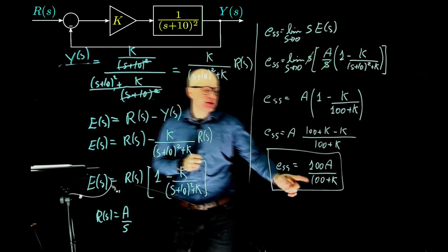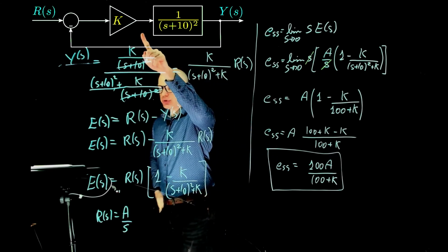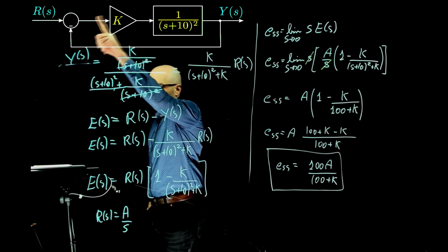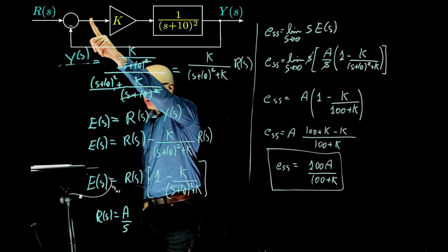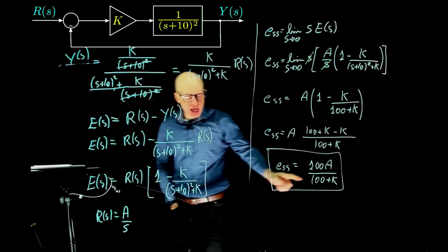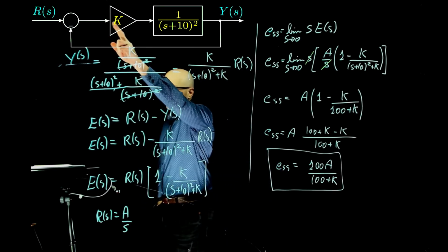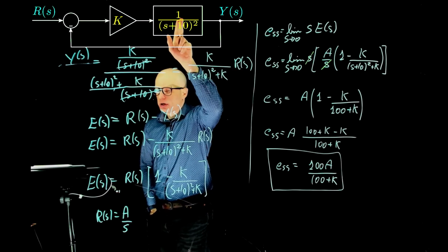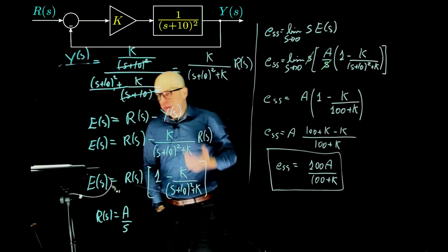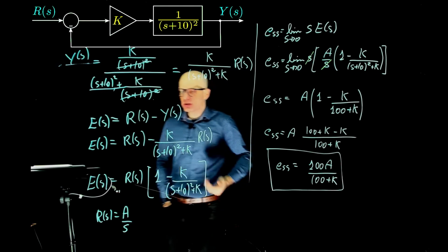Well, the problem is that K is the proportionality constant that gives the amount of drug we are injecting in the body compared to the error between the input and output. So if K is too large, then a very small deviation here would inject an enormous amount of drug in the body. That would not work for practical reasons and for safety reasons.